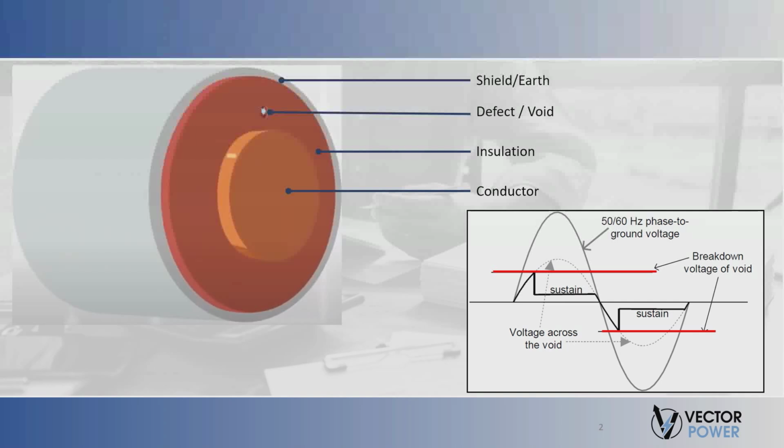Partial discharges are tiny electric sparks that can occur at defects in insulation, along interfaces, or surfaces between a conductor and a floating conductive component, not connected to the high voltage conductor or the ground, or between floating conductive components. When the intensity of the electric field is strong enough to ionize the medium surrounding these components, partial discharges will happen.